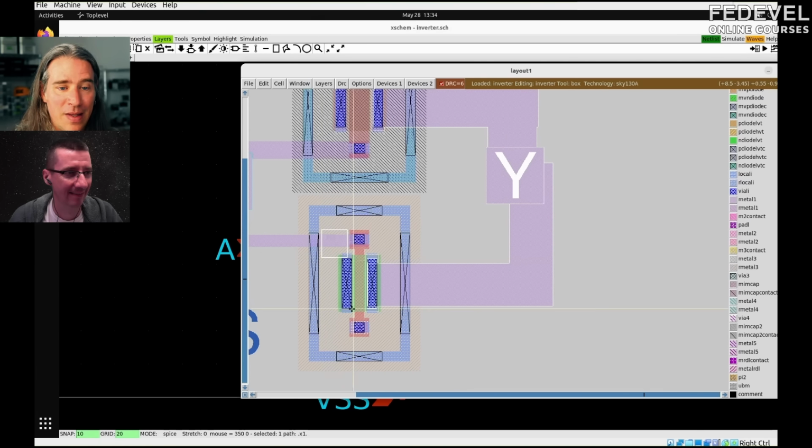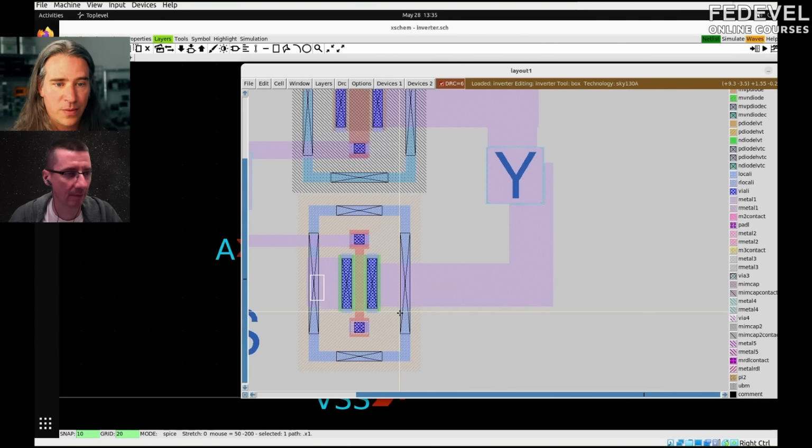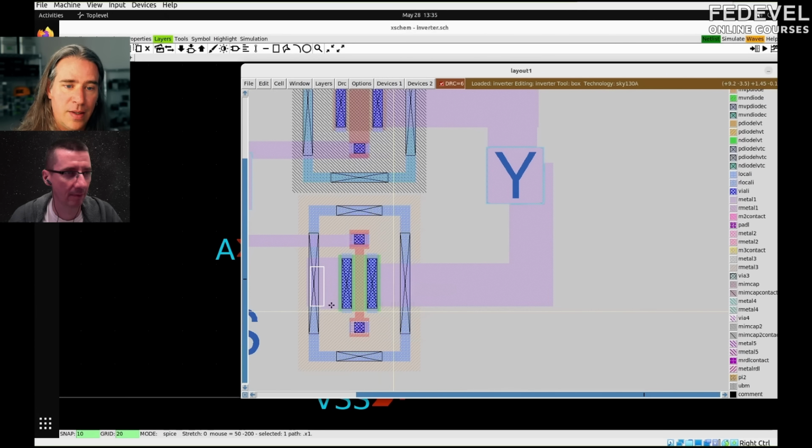Let's escape. Let's get out of here. So I have to get down there and I have to get out. So I'm going to paint this in metal and then go to layer 2. I'm going to grow this box. Okay, grow it. So exactly what I did there, the via 2 or via 1. Via 1. And it didn't want to because my box is too small. Again.